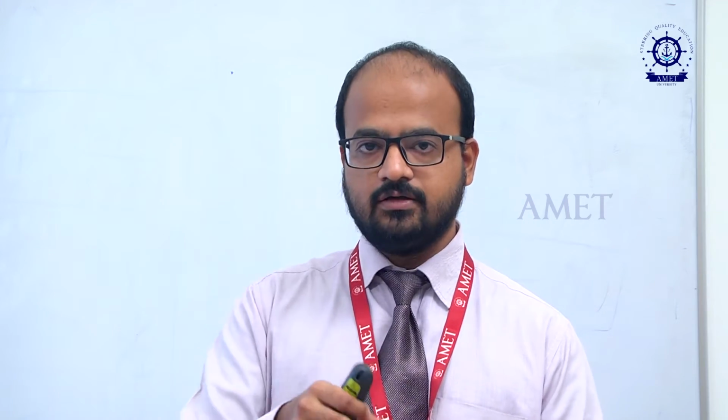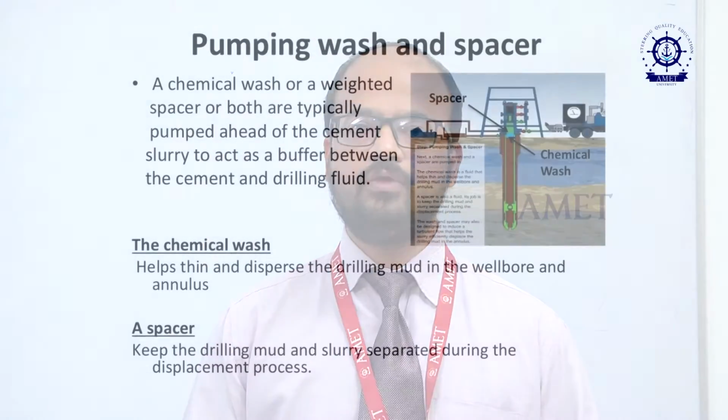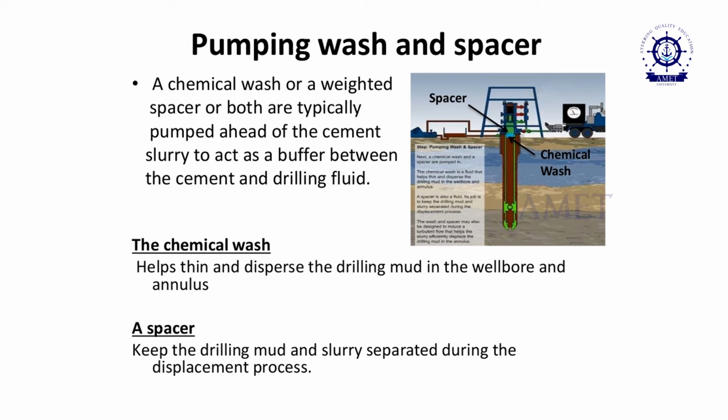As I told earlier, if you put drilling fluid followed by cementing, or cementing followed by drilling fluid, it starts to mix together and contamination will be created, nothing will work. Our ultimate aim is to completely wipe out and remove the drilling fluid from the entire well, and then pump the cementing. If you do that, the cementing will be completely sealed in the formation. So for that, we have to use this spacer.